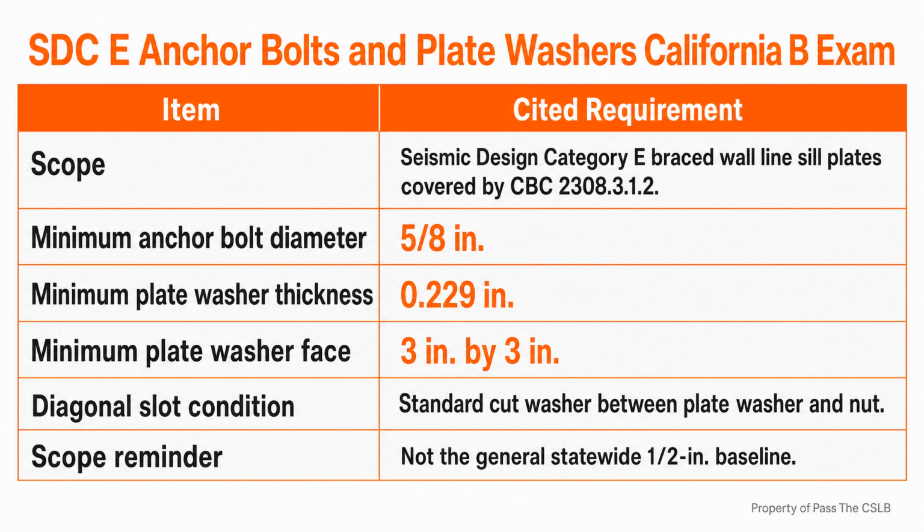A crew habit, a remembered detail from another project, or the nails already loaded in a gun do not override the project documents. Suppose a crew installs an engineered vertical frame at an open first-story line but uses ordinary framing connections, where the plans specify a higher capacity transfer connection from the floor diaphragm. The frame may be anchored beautifully to the foundation, yet the upper floor force still lacks the approved handoff into that frame.